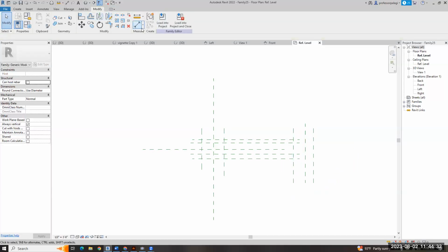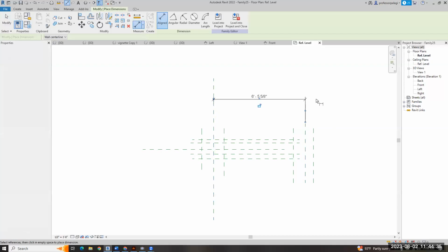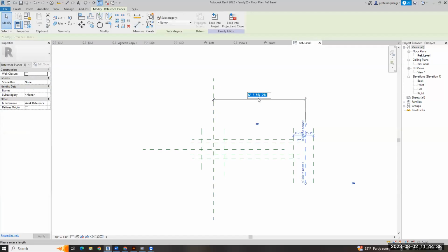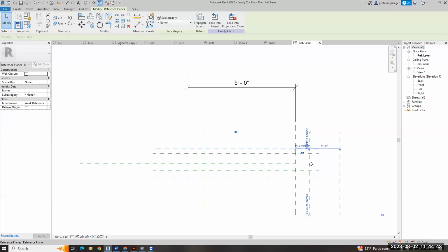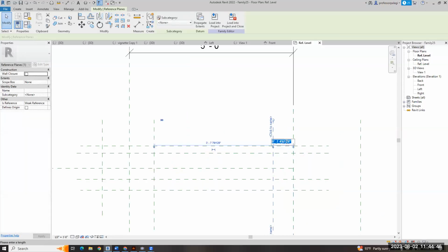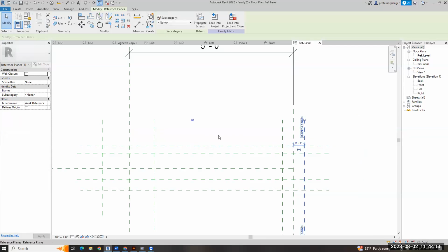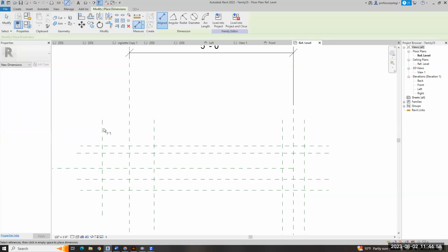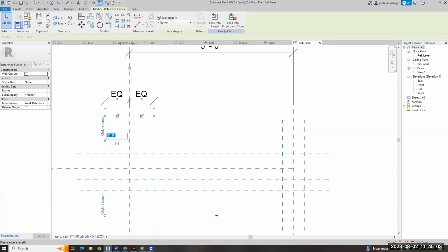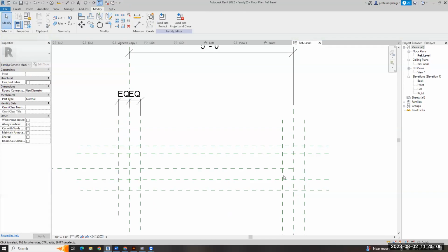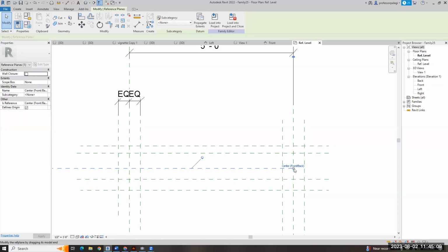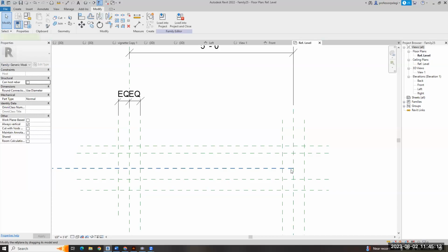So let's start to get these dimensions where we want them. This is 5 feet, and it'll make sense in a second, because the whole thing is that this is a 10-foot bay, but remember that the bracket arm reaches to the middle of the other thing, right? And I'm going to say this is like an 8-inch total. So that's 4 inches there, 4 inches there. We can do this really quickly again by just saying 4 inches there. Okay. So I'm just kind of thinking through this, the center line of the whole thing. I'm looking in plan right now.